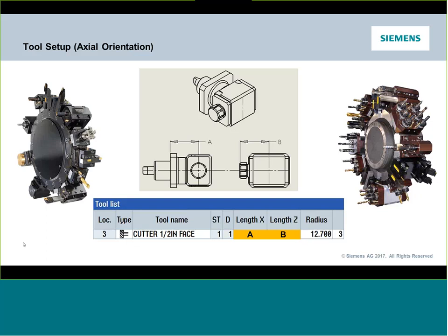If you look at that left turret again, down here in pocket 16, it looks like a Sandvik turning tool. This is set up most likely to cut on the back, the sub spindle side, so I would expect to see a negative offset for this given tool. If I look at my boring bar, a couple spots down, I'm going to expect to see a positive value. Again, that number is most likely going to be the distance from the center of the holder out to that cutting edge, and that would be my B dimension.